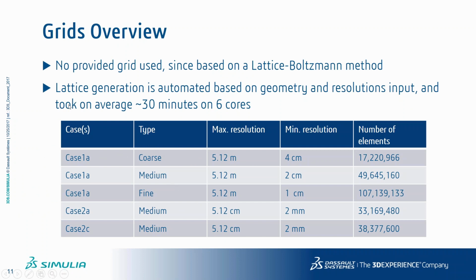So these are the lattice we used. Okay, so it's an introduction. Again, it's not exactly a mesh, but imagine that's basically the mesh we use for our CFD analysis. And you know, the committee for these workshops usually provide a mesh that all participants need to use, for all Navier-Stokes codes, or are, well, invited to use at least, because of that we can compare all participants in a fair way with the same meshes and just see the impact of the solvers independently of the mesh. We can't do that, okay, because we're a lattice Boltzmann method code, and consequently we had to generate our own lattice structure because we don't work on meshes, okay?